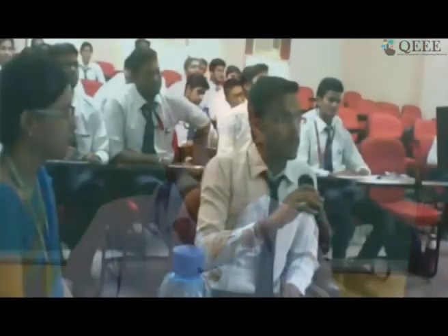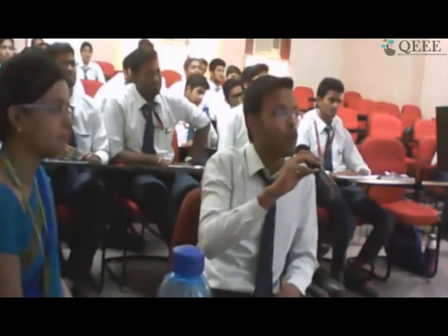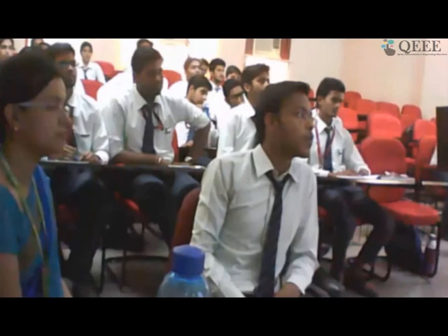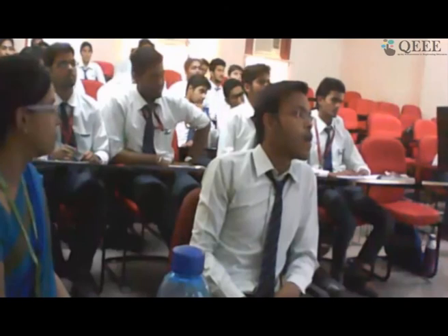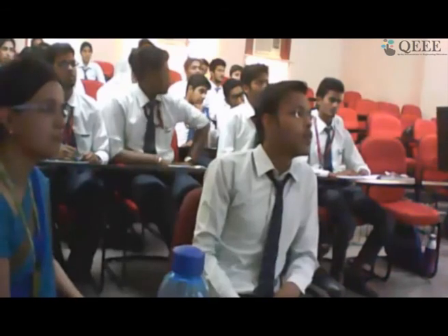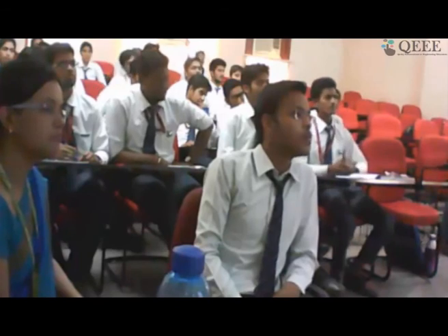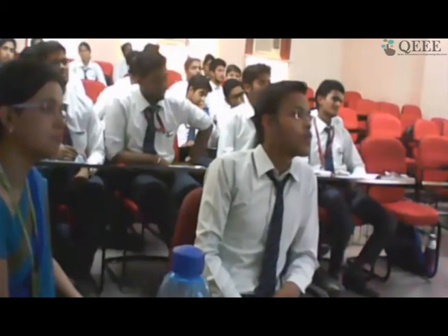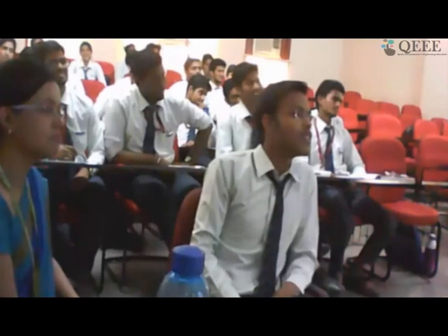and then cover the corroded bar again. But does the deformed bar increase the ductility of the bar as compared to a normal or plain bar? Ductility is a function of the microstructure of the steel. Okay, so are you talking about cold twisted deformed bars? The normal deformed bar available today, which we call TMT. So those deformations are done mainly for the bond. The ribs you are talking about, right? Yes, sir. So ductility is a function of microstructure.